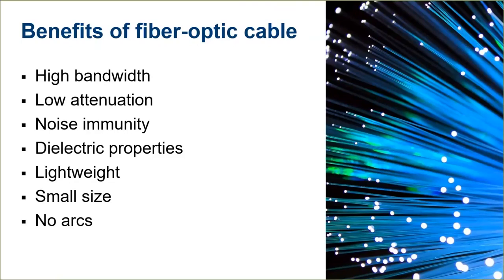Most fiber optic cables are constructed from all dielectric materials that are usually suited for installation in most any electrical environment. Because the fiber optic cable is very compact, lightweight, and very easy to install, it is also feasible and very common to install excess capacity during the initial installation of fibers. Many electric utilities install fiber optic cables inside their power system conductors.